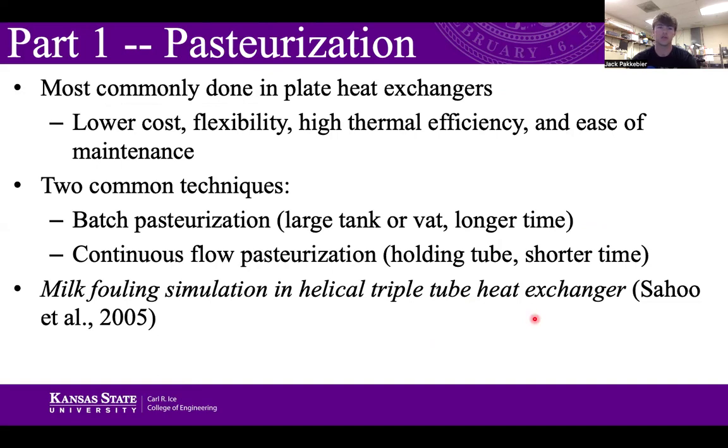So going into a little bit more detail about pasteurization for part one. Most commonly, pasteurization is done utilizing plate heat exchangers. Plate heat exchangers offer a lower cost, higher flexibility, higher thermal efficiency, and a greater ease of maintenance compared to other heat exchanger ways. There's two common techniques for pasteurization. You could either operate using batch pasteurization or continuous flow pasteurization.